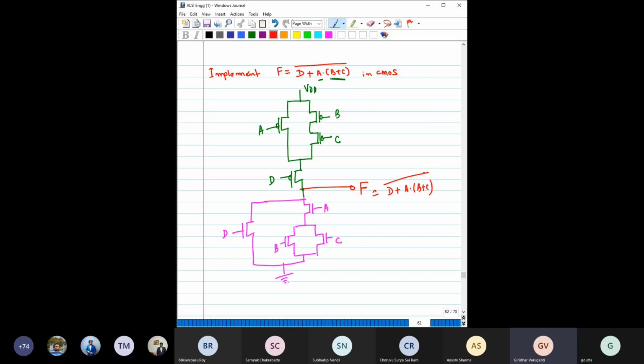So we can also draw this like at first we will draw B plus C whole bar, then put the output into another CMOS inverter, then from the output we will get B plus C. Then we will AND that output with A. Right, but then the transistor count still remains. It will be multi-stage, no? Multi-stage means you can make multi-stage, but if you make a single gate using multiple stages, then what will happen? You have this stage delay, this delay, this delay, right? Yes, it has to be calculated.